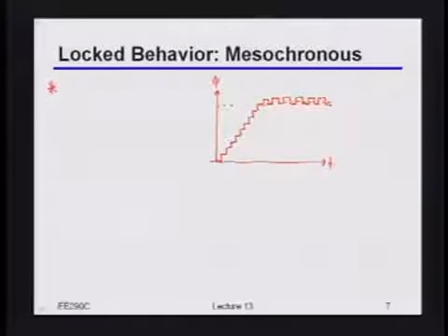Yeah, there we go. Okay, so the first thing you care about is just the worst case step size, right? Because if I have some basically DAC-looking thing, which is that phase interpolator, which is just translating digital codes into phases, and I know that I'm always going to be jumping back and forth, then what I care about is what's the biggest jump that I could possibly be taking. Because that sets the magnitude of the dither that I'm going to be getting in my system. It's absolutely true.